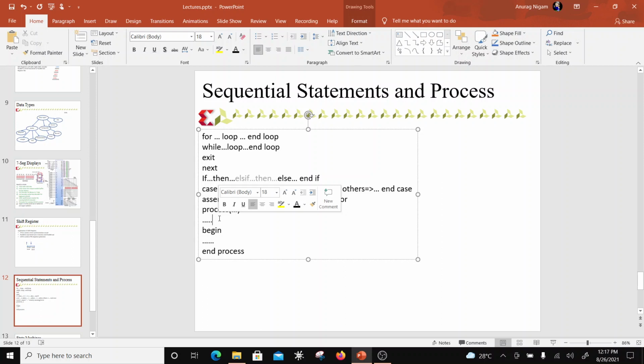And if you mix the two, then you have a very complex engineer, difficult to handle, because he's thinking that everything is like, if you design a counter, you will say count equal to count plus 1. So then he would be more like a Verilog or a testing guy. But if you ask for a designer, then he will be more like a VHDL guy. He would put in flip flops, T flip flops or JK flip flops, and then he would put a structural design to a counter rather than saying count equal to count plus 1.